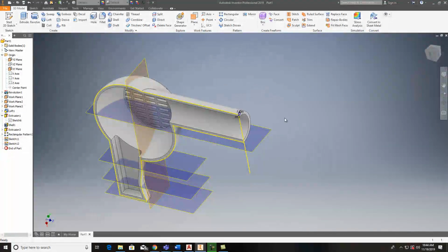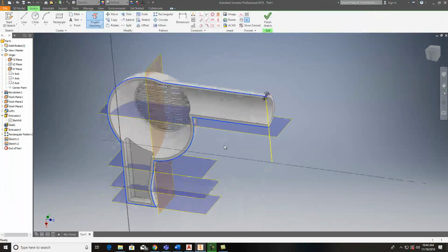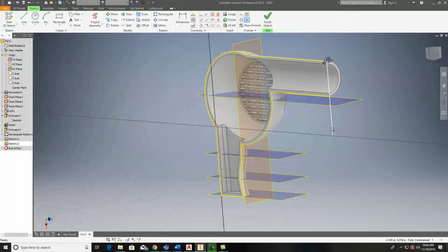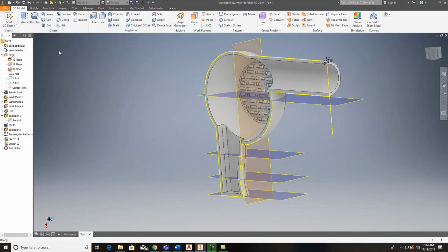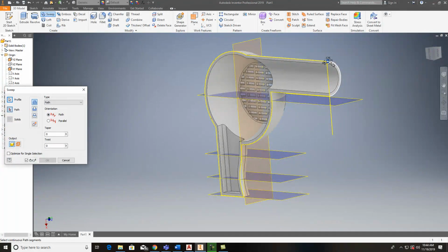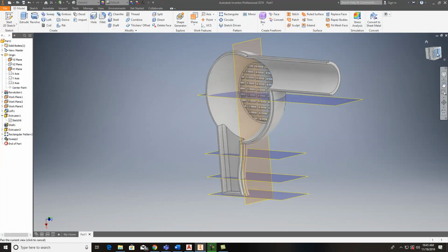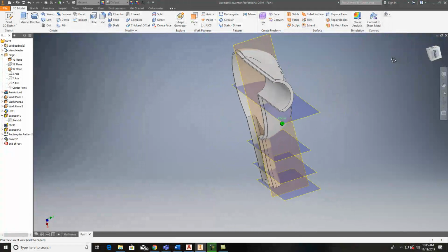So finish your sketch. And accidentally edit my sketch. This one got put in here. No, that's my plane. I believe that's my work plane. Let's see if I can delete that. Yeah, that must be my work plane. I was just checking that out before I started to try to sweep. The sweep takes your profile, your enclosed profile, and then your path would be that line right there. You see how it's following that path all the way out? So just hit OK on it. Make sure you cut and hit OK on that. It cuts it out. And now you have that side of it done.